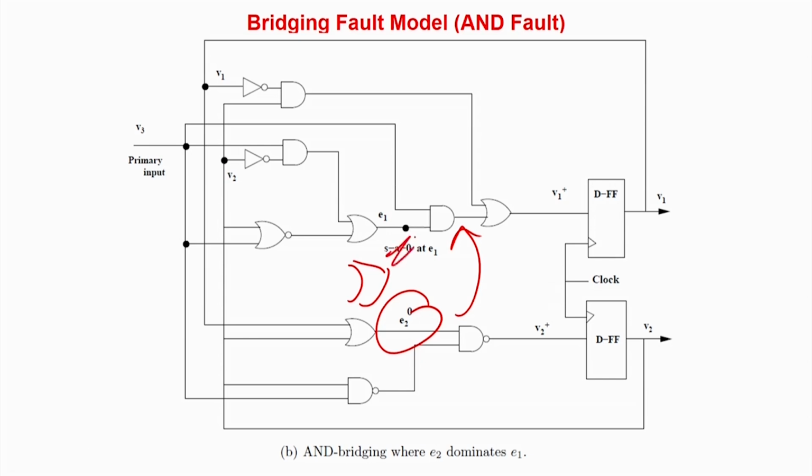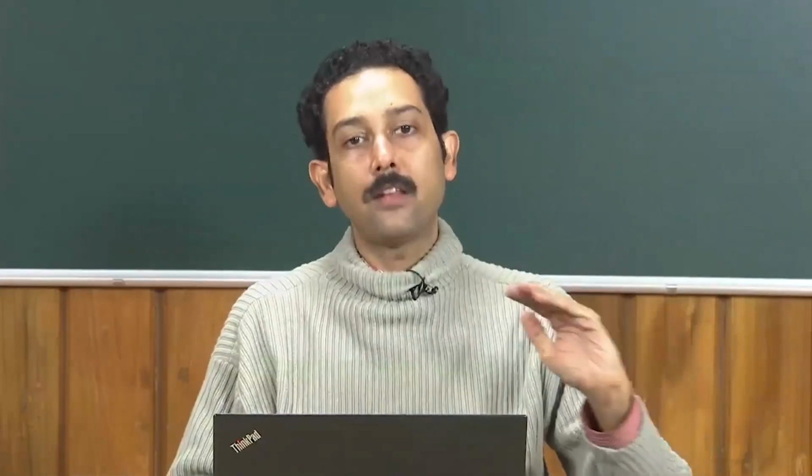So in this case you will be assuming the stuck-at-1 fault over here, and here you have to explicitly have the value 1. That is a dual you can easily calculate. So basically what happens, again I am repeating the key terms here, if you go for testing the bridging faults, automatically you will find out that a lot of stuck-at faults are already getting covered.